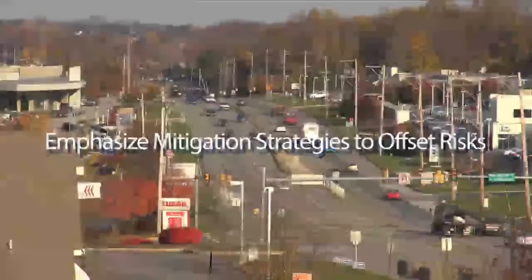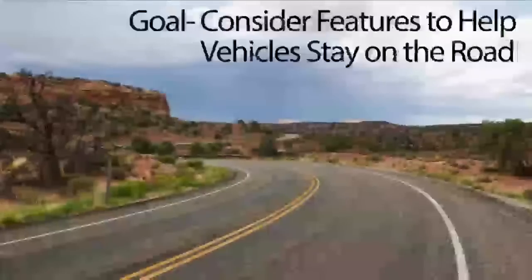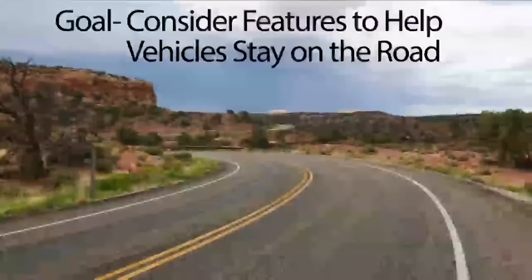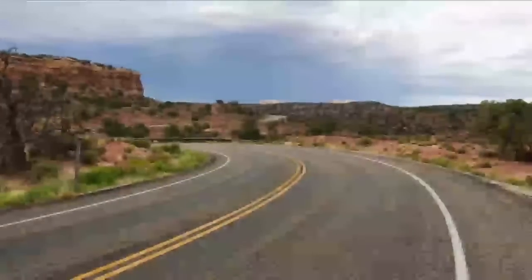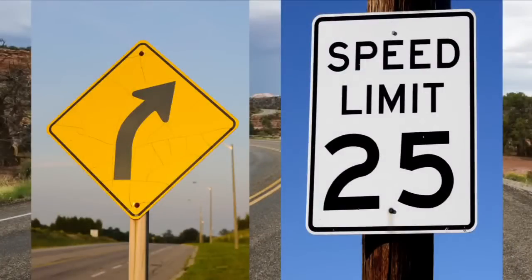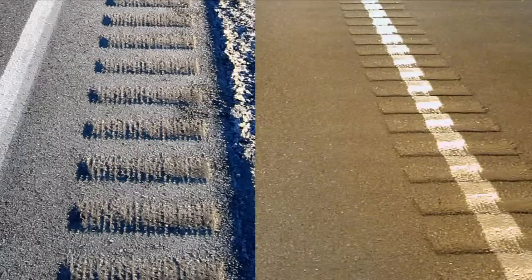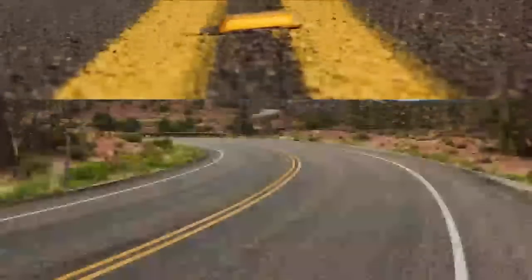For example, what mitigation strategies could you consider to address a sharp, substandard curve ahead? In this situation, your goal is to consider features proven to help vehicles stay on the road to mitigate the risk of building a substandard curve. In this example, you could address this situation by including mitigation techniques such as the installation of warning signs or speed plaques, widening the roadway or shoulders, installing rumble stripes, adding superelevation, or incorporating a skid-resistant high-friction pavement surface.